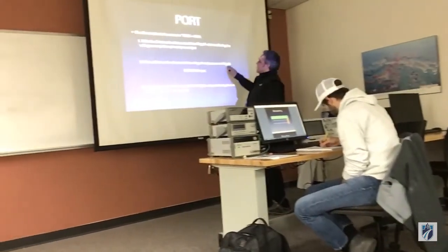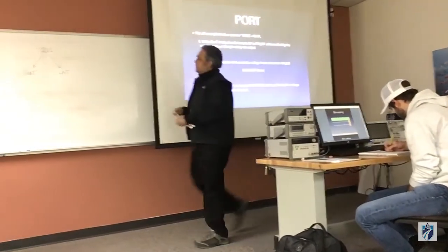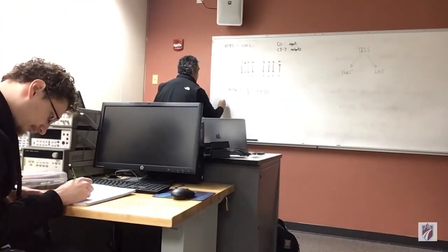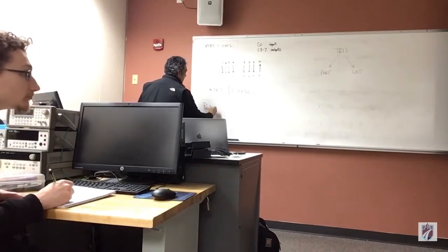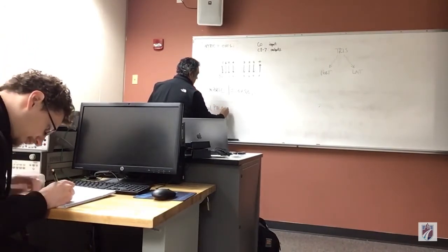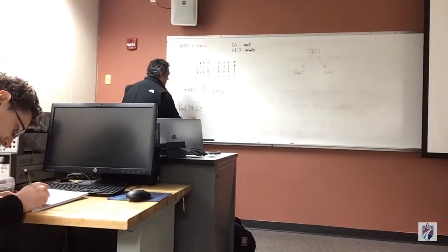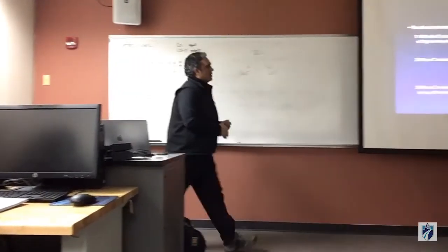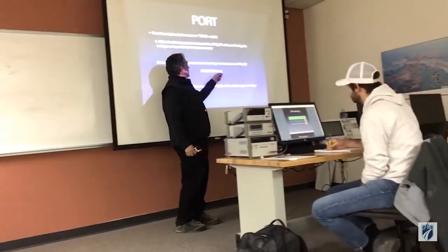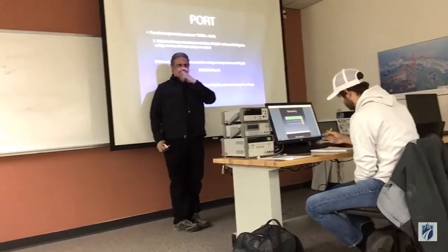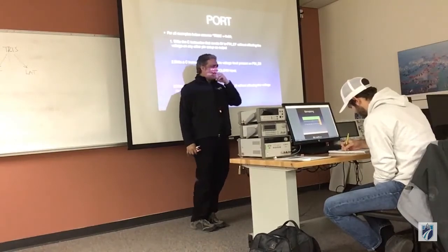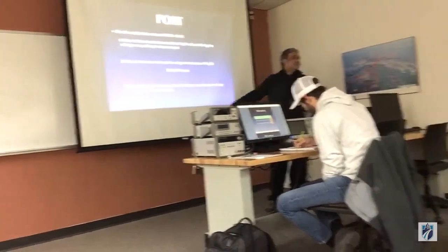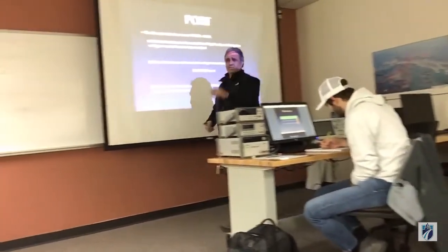Okay, so how do you read pin C0? Well, I'm going to use a read operation. So I'm going to put here read pin C0. I'm going to take input as the variable that is given to you. A Boolean variable means that it's a single bit variable. It exists in CCS, Code Composer Studio, which has the Boolean data type. It's just a single bit. That's all it is, right?